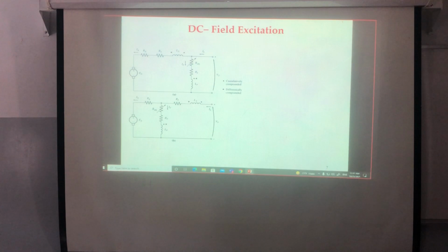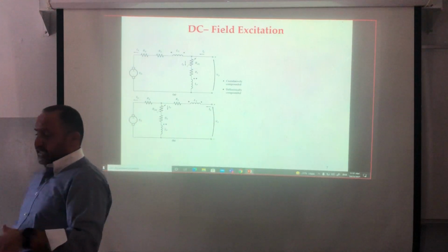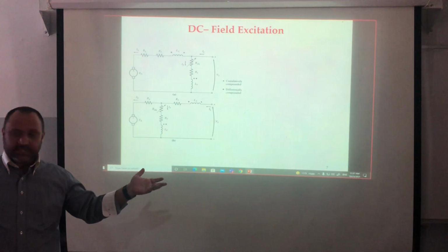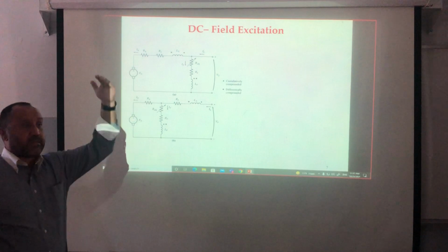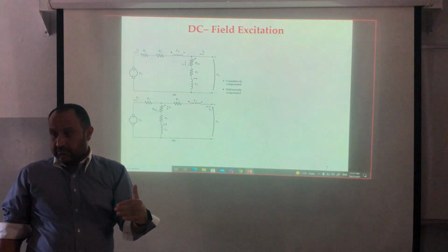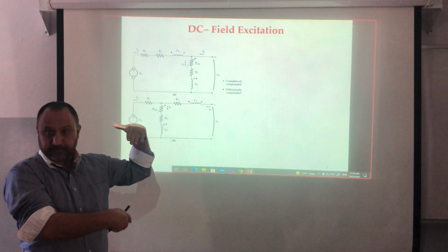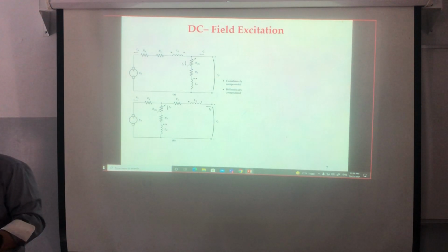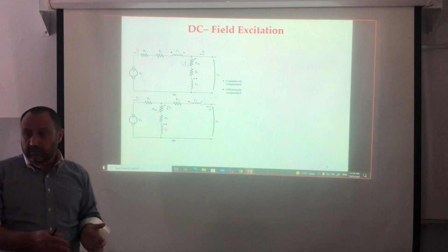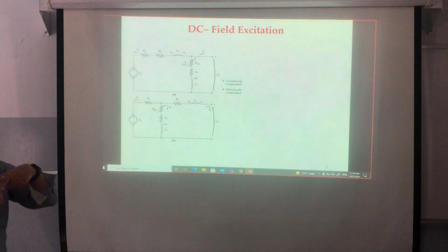Now what about if I need to merge the advantages of the torque speed characteristic of the shunt, or the separately excited, and the series? In the shunt, if I'm neglecting the armature reaction, I'm having a linear torque speed characteristic, correct? I can operate at no load. For the series, I'm having huge starting torque, but it's forbidden to operate at no load. So what about if I combine them? This is the idea behind combining the shunt and the series field.